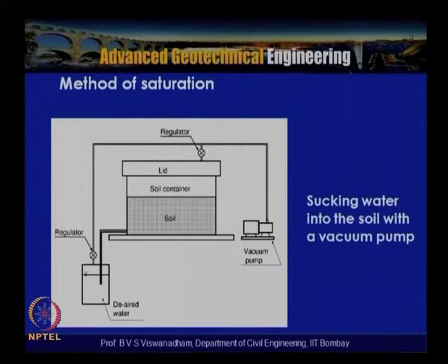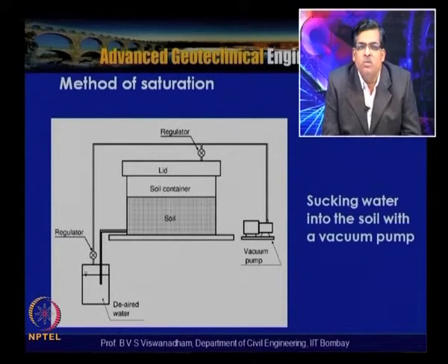But when we replace water as the pore fluid, even to saturate a fine sand, special saturation methods are required, and they also take a long time. And if you have layered soil, or clay and silt, or silt and sand layers, sometimes it is very difficult to saturate with high-viscosity pore fluids, particularly if you have a sand with up to say 20-30% fines. There is a possibility that the saturation may take longer and special methods may be required.